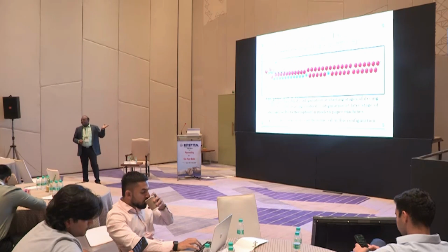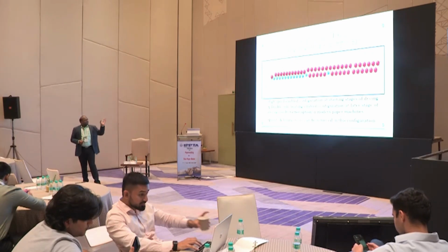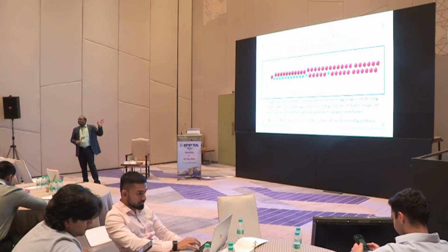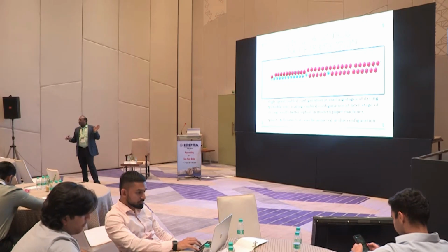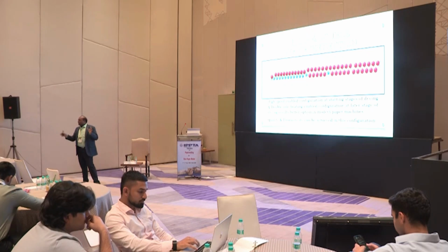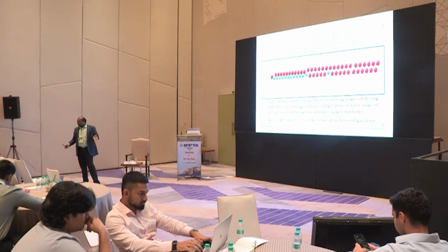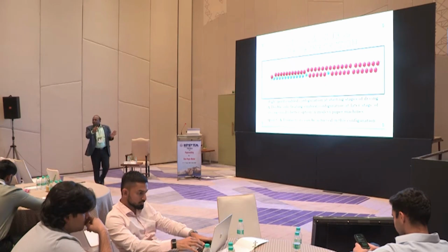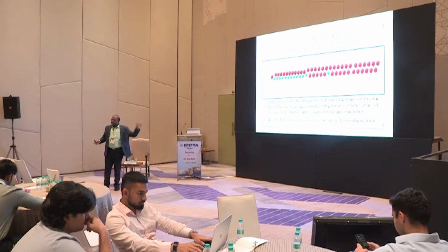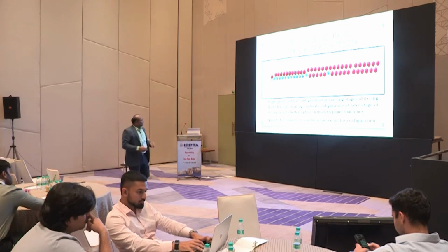Again, that invention and technology upgradation has come. Since in the initial stages the web will be moist, it will not have that much strength. So for the first 2-3 stages the design will be kept as single tier. Once the support has come and the paper has dried and the strength has come, again the 2-tier concept is used, and the curling issue is also solved and the speed also increased. This is the next technological advancement.